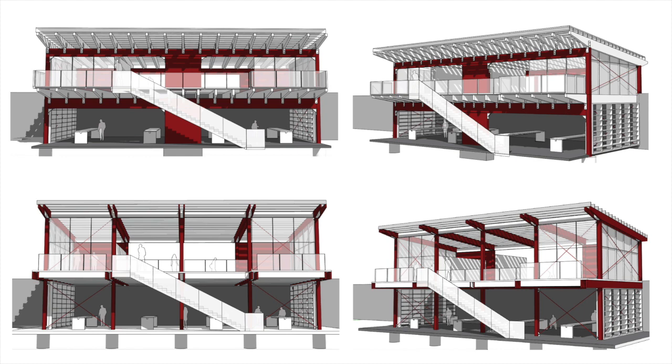When you look at these particular options, so on the top you have 2A, on the bottom you have 2B. 2A on the top is where we have a girder on the front face in red, the purlins that are cantilevering out. You can see the value of that stair being moved to the front. We get our lateral bracing with the CLT wall panel in the middle. We get the bracing on the two ends with the X bracing, you can see there, and the bottom side there. But in doing so, we really define two big open ground floor spaces down below. We're able to define the classrooms on the two sides there, really open it up.